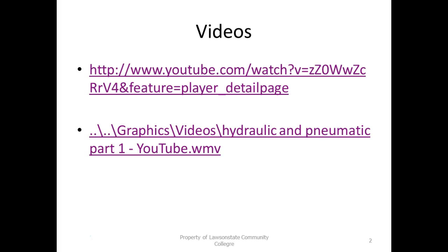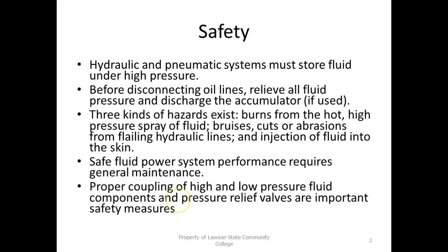And we can control the speed by controlling the flow. So some safety: hydraulic and pneumatic systems use stored fluid under pressure. And of course, anytime we have pressure, it's trying to push things out, right? So we have to be cognizant of that. Before you connect any lines, you want to try to bleed off the pressure, especially in a hydraulic system.